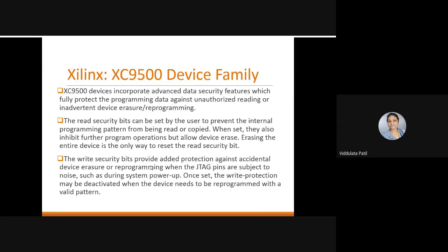That means no one can read without authorization, or erase the programming, or reprogram the device. Then the read security bits can be set by the user to prevent the internal programming pattern from being read or copied. So there are certain read security bits that the user can set so that these patterns cannot be read or copied.